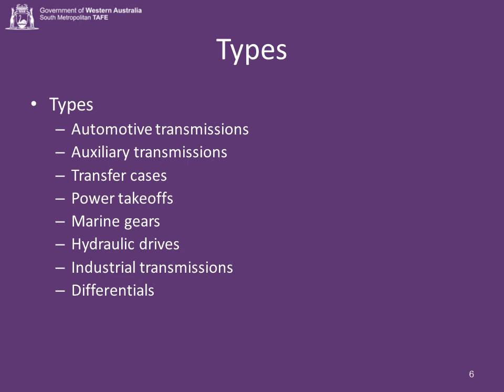Auxiliary transmission is usually installed behind the main transmission to increase available ratios. Sometimes this was called overdrive. Transfer cases. These provide additional power outlets, such as for the extra two wheels in a four-wheel drive, or provide offsets from normal drive lines. Power takeoffs. These are usually mounted beside the main transmission and driven by an additional gear. These are often used in agricultural systems to provide power to machinery.